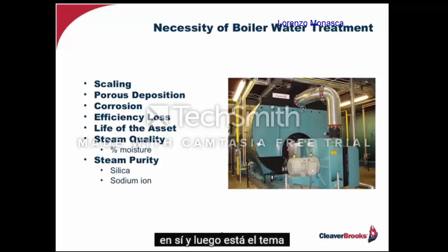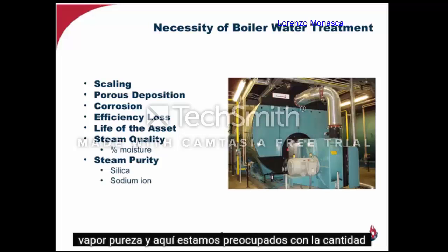And then there's the issue of steam purity. And here we're concerned with the amount of non-water components contained within that steam. Now that's usually measured as sodium ion and silica, which if present can certainly cause havoc within the many systems that we encounter.